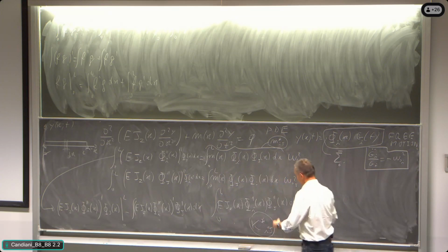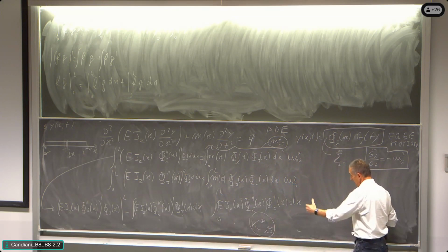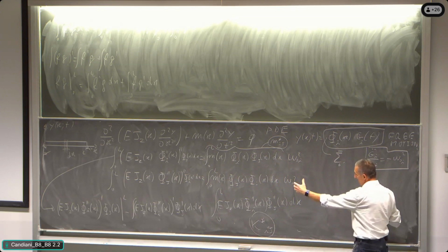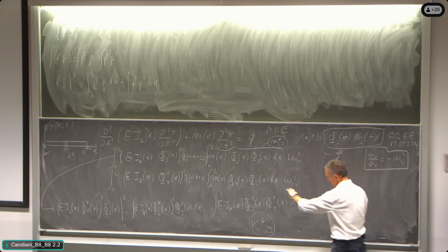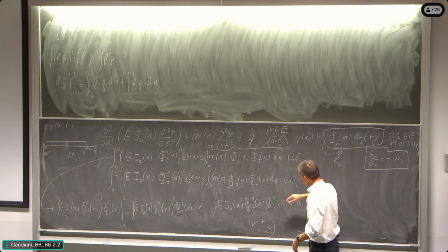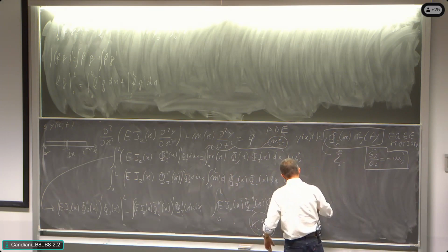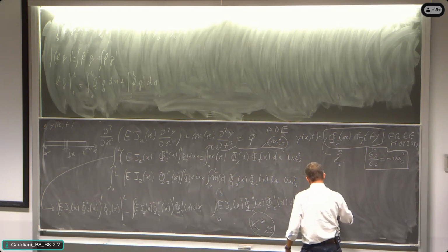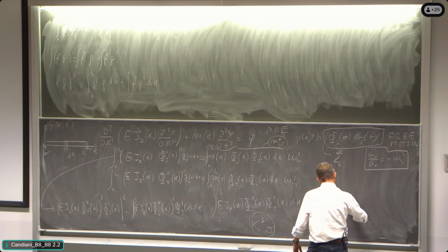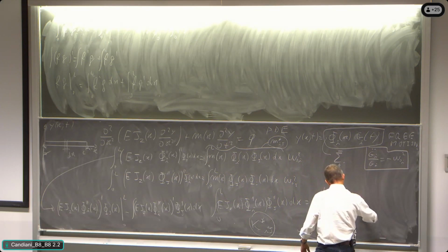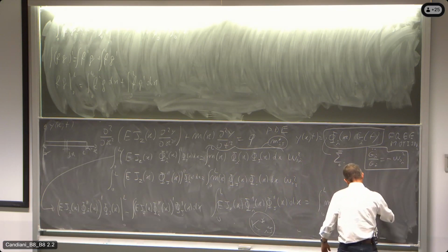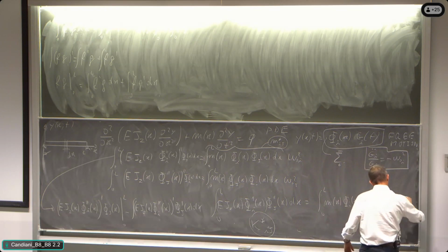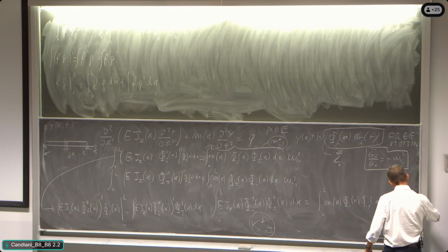And so finally, making the integration by parts, we are working out and finishing this procedure, saying that k*_ij, on the left side, is equal to the integral from 0 to L of m(x) phi_i(x) phi_j(x) dx times omega_0i squared.